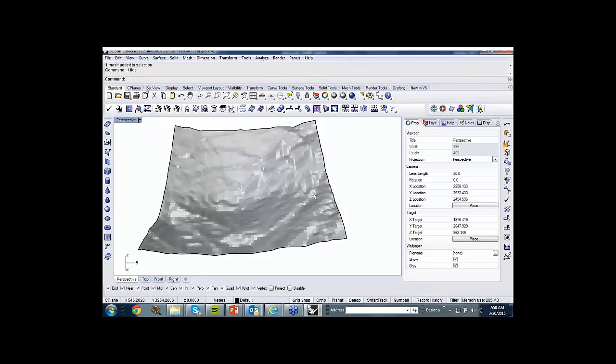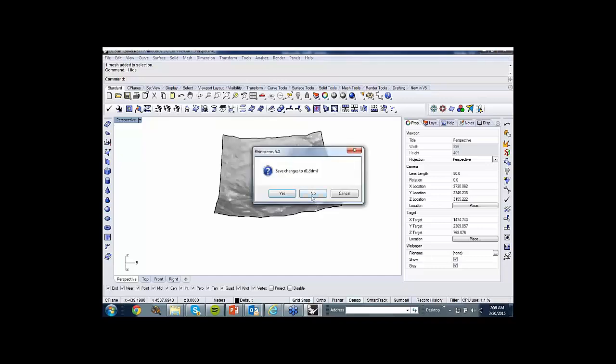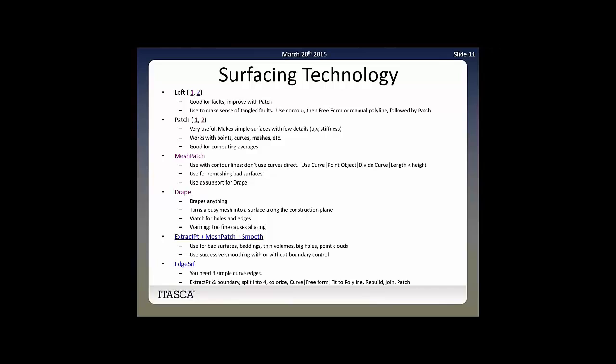If you make it too fine, it creates unrealistic features on the surface. So there's this issue of aliasing, like the Nyquist criterion for sampling signals. You don't want to oversample. You may have consequences from it. So don't be greedy. Make a simple surface, and then later on, if you need more, make it finer. The payback from making simple choices in the shapes is so much more important, so much more attractive.